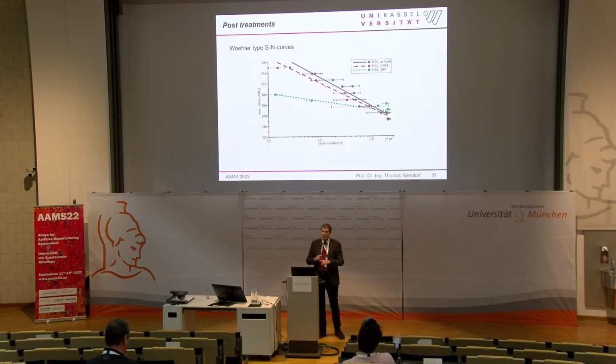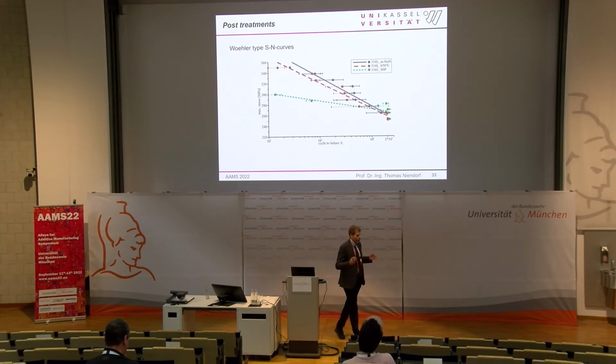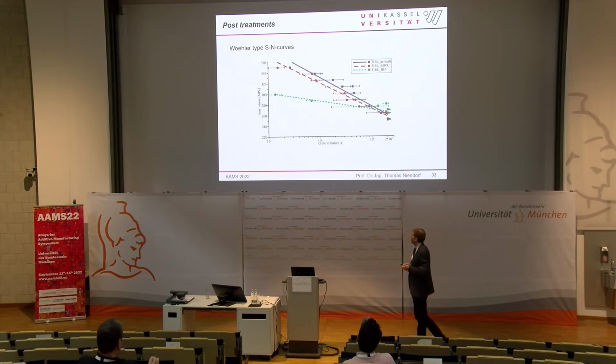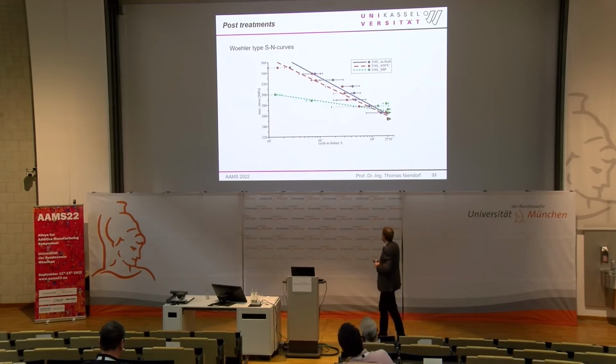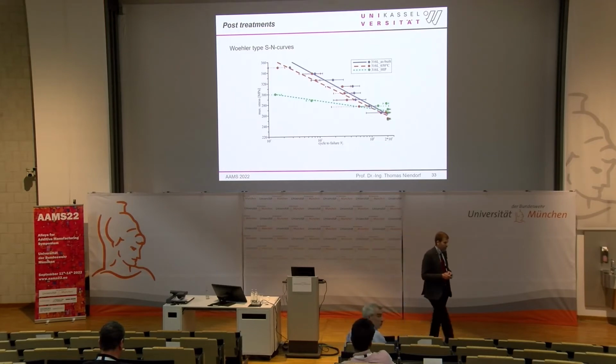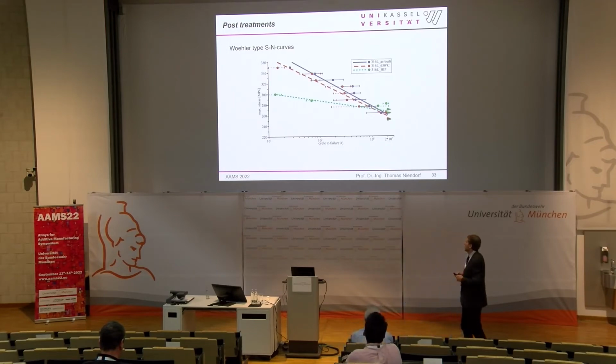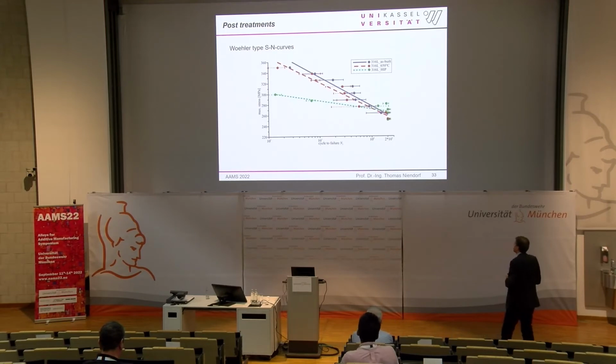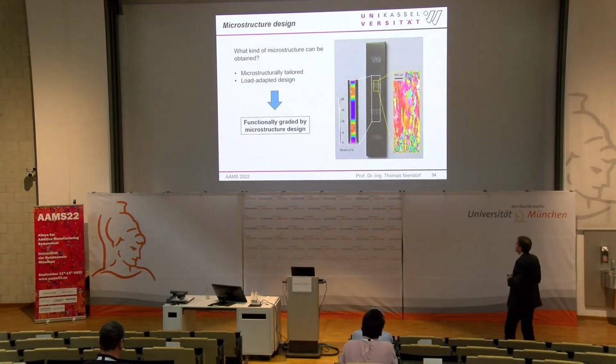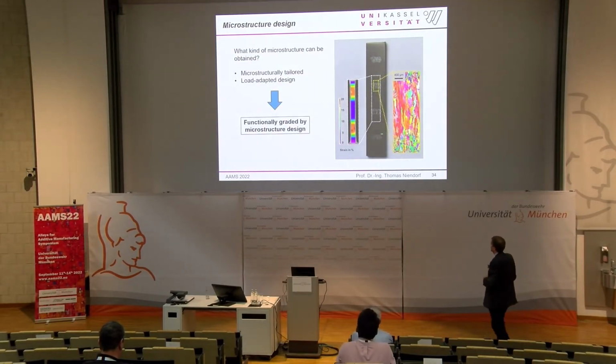Because recrystallization just erases all the information we had before, so including those subcells, we lose performance, we lose strength. So in terms of fatigue, it should be considered if HIP is the right thing to be done using 316L at least. This should be avoided as well when it comes to graded structures. So I was fascinated about microstructurally graded structures as well. So we printed this block 316L.